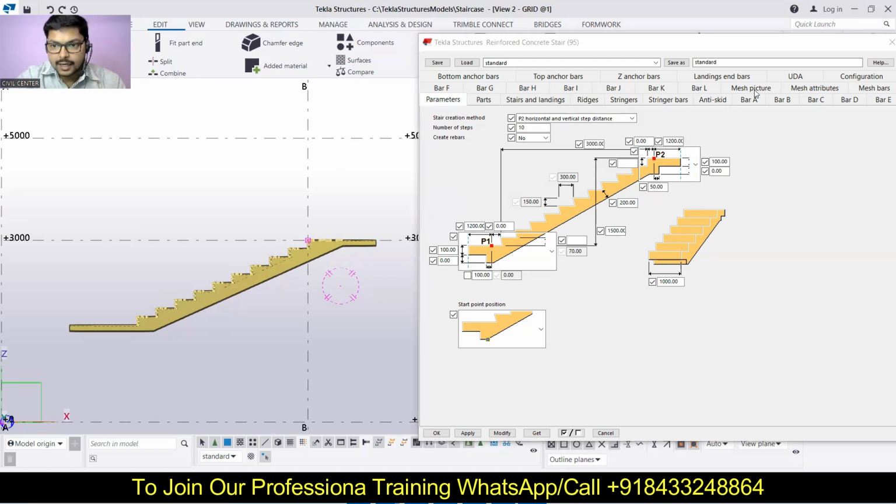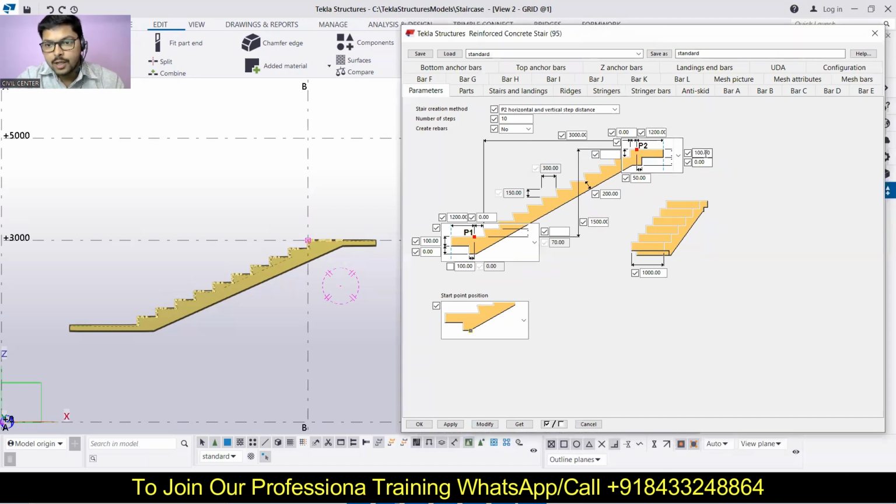We have already defined all the parameters over here, so now I am going to explain all these parameters to you. Here I have selected the slab thickness as 100 mm, and then this landing as 1200 mm. Then this height I don't need, so I have not defined this one; I've kept it 0. This going was 3 meters, so I am putting it as 3000, then this height was 1500. And the width of the going was 1000, and all the modifications are right over here.